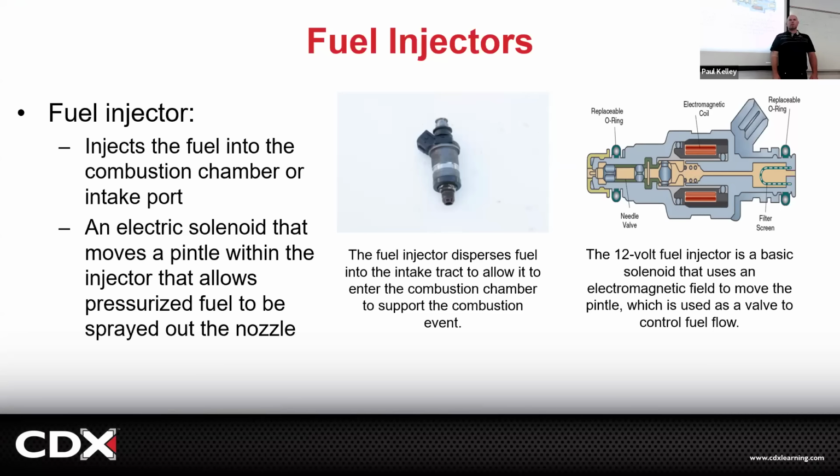Make sense? What if for some reason the injector needle and seat got kind of messed up and it wouldn't seat all the way and it was leaking? What would happen? Spray way too much. It would spray all the time. As soon as you start the car up, it's just spraying and spraying and spraying. That's going to have way too much fuel in that cylinder. That could cause a lot of other issues, black smoke, maybe even a misfire, potentially damage that cylinder, right?